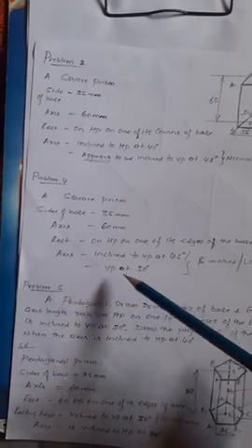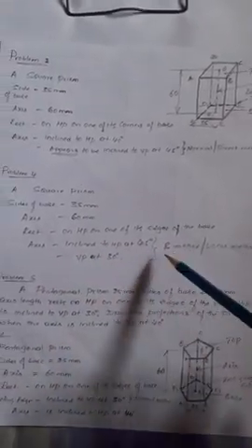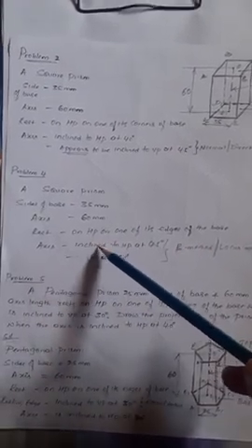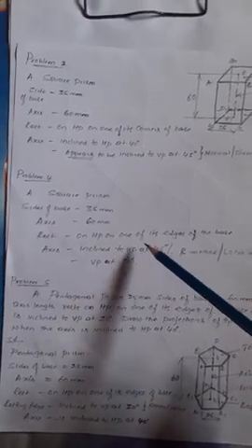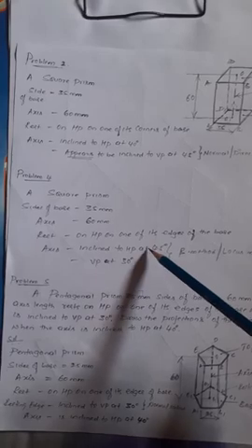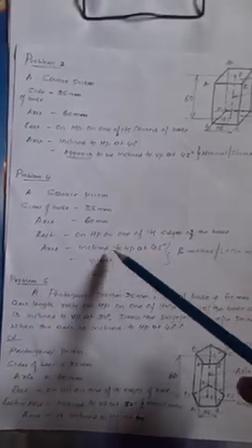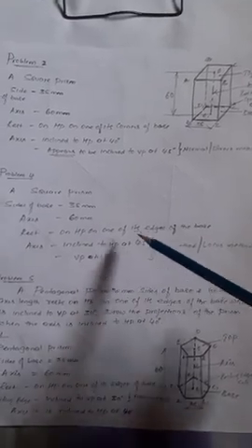Now, which method does this problem come under? Beta or locus method. Why is it the beta or locus method? In the first position, we get the true length of the axis in the front view, and in the second position the front view also gives the true length, but in the second position top view, the axis is a reduced length, that is, the apparent length. That apparent length is inclined to VP at 30 degrees, which means it comes under the locus or beta method. We know how to solve this problem, right? Now we'll move on to the next problem.